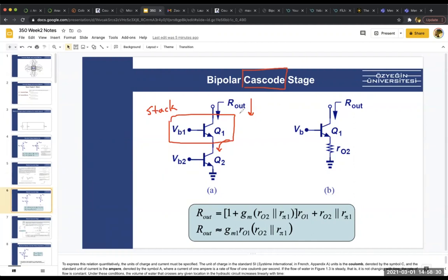The reason we did this is because we brought much more isolation to the circuit. Bringing in this Q1, you are isolating this transistor even more, and that boosts your R out. How is it boosting your R out?